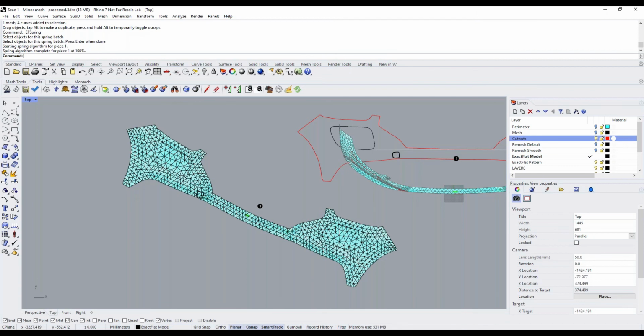So you can measure perimeter edges in 3D and 2D. That's one way of checking the fit. You can measure surface area between 3D and 2D. It's another way of checking the fit. You can print a paper pattern, plot a paper pattern, cut it out, wrap it on the object in question, and you can see how it fits. And as you get confidence that it's going to work 100% of the time, then you don't need to get it tested each time you go off to get it cut.